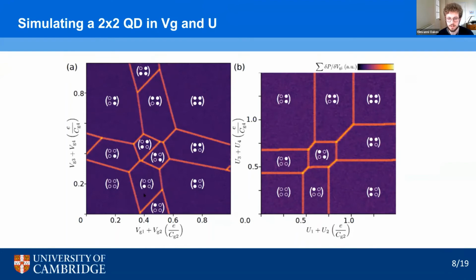And instead, if we then move to its virtual voltage state, a lot of these interdot charge transitions disappear, and our dot-to-reservoir transitions become perpendicular, making it much easier to interpret and also navigate in order to then arrive, for instance, into a state where we have a single electron in each quantum dot, which is what we'd probably want to be in order to initialize our quantum algorithm.